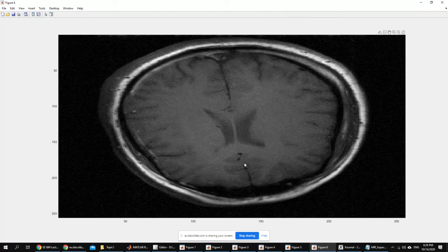So basically, the conclusion here from this quantization experiment is exactly like what we said before. For quantization, it depends on the kind of image that you have, and you have to look at the quality yourself. You cannot say that a number of quantization levels of 6 bits or 8 bits or whatever is sufficient. No, you have to actually experiment with that for each type of images on its own. Okay, you cannot just generalize on that.